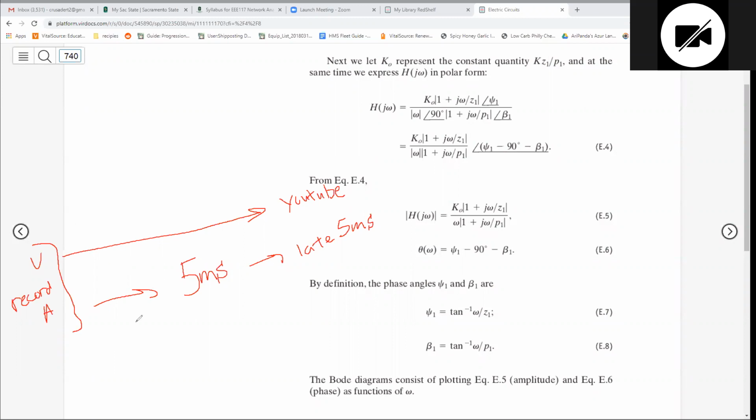So basically, anytime you have parallel systems like video and audio, you have to synchronize. So we have to synchronize these, right? And that's where a lot of filters and everything else comes in, okay? So in this case, phase angle matters a lot because you need to make sure the phase angle shift is not too much. If it's too much, we're going to notice. So we need to make a very tight phase shift for audio in this case. Or we have to introduce a 5 millisecond delay right here. One of those two, right? You have to sync up your audio and video, right?